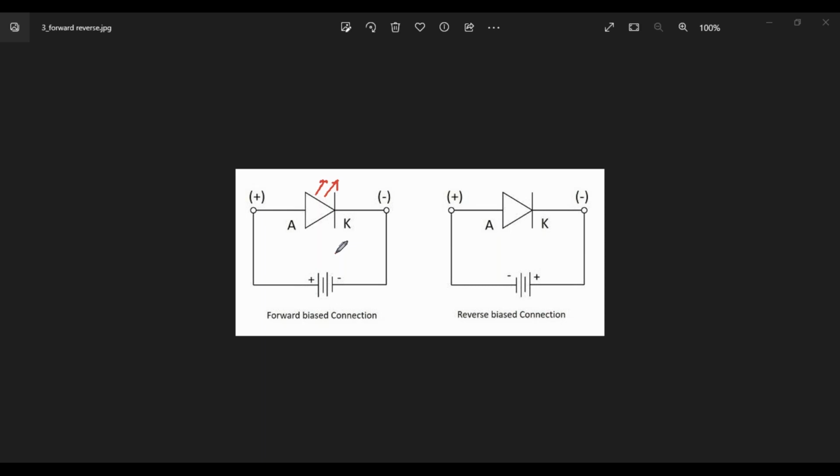Yes. So what happens if more than the required current is flowing via this particular diode? Obviously it is going to get damaged. Okay. So the LED is going to get damaged. Then how to sort this out is, you have to add a passive device which consumes the current, and you should not let the device get damaged. So I should have a resistor added.